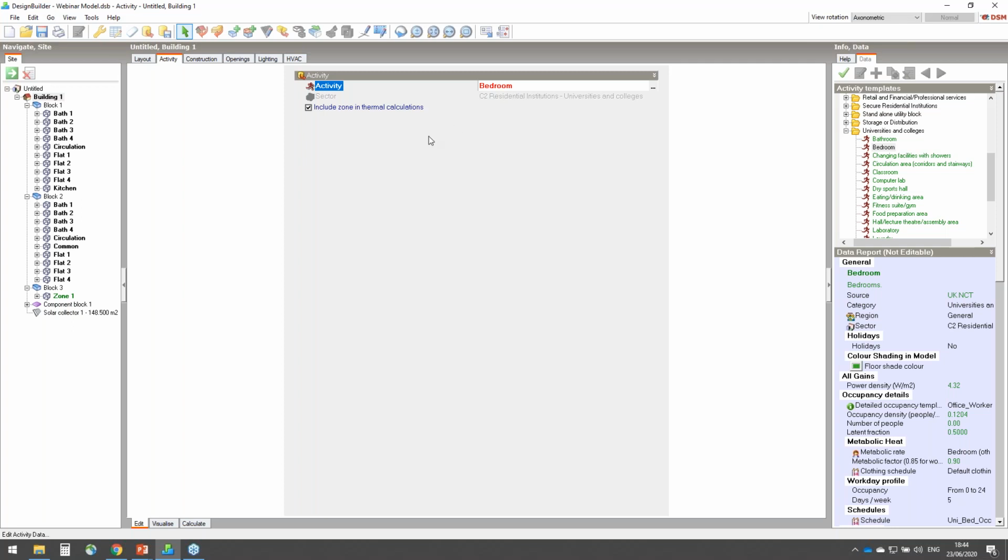Some of the Design Builder users might notice that there are fewer model data input fields in the activity tab. This is because we are in a DSM certification mode that is specific to UK compliance, which does not allow modifications to occupancy or loads. So the additional data is locked and hidden. You will see the difference between this and the performance modeling shortly when we switch to the full EnergyPlus mode, where you will have much more flexibility to input accurate information and not be restricted by NCM default data.